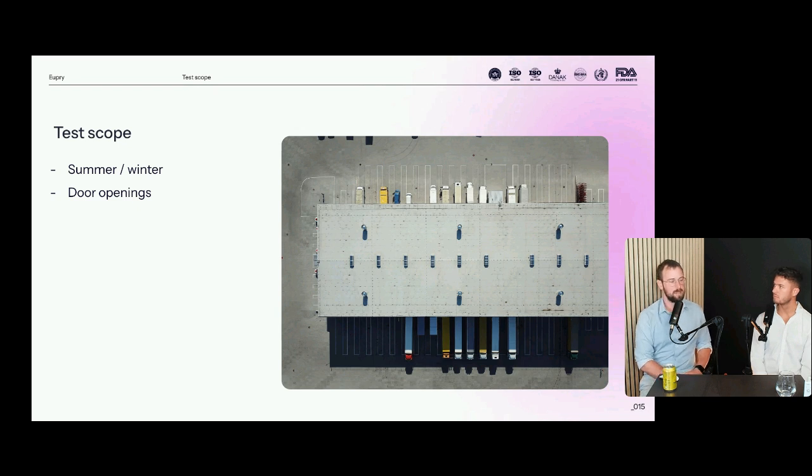And we'll get back to this in terms of when to perform remappings. But basically, if you have performed a mapping in which you test, let's say 20 times a day, 30 seconds per time, and you start changing that to 60 seconds per time, 100 times a day, that is a major change, and you need to perform a remapping in order to ensure that that does not pose a risk to the product stored.